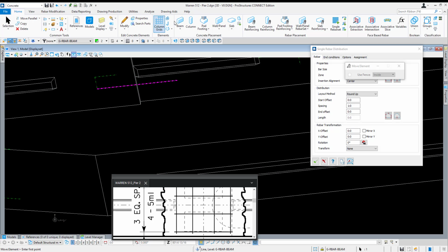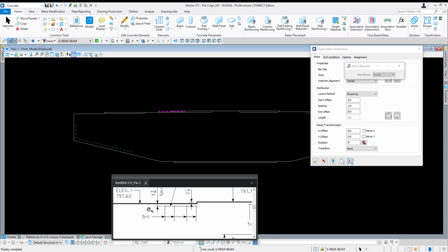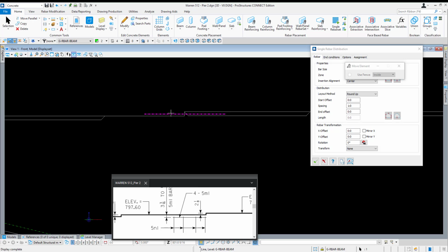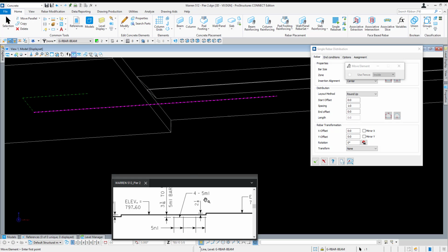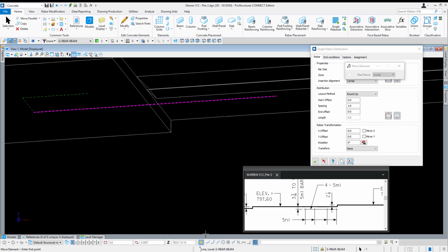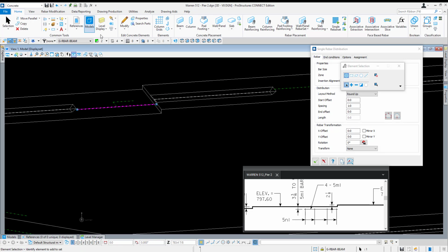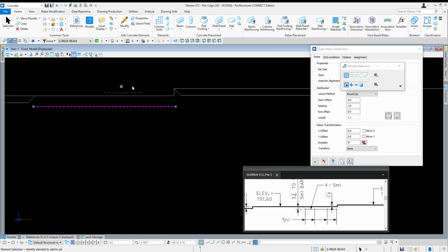Now they are number 5, so right off the bat I need to make sure that I have my clearance values right. And for this set, we need to be 3 3/16 to center line of the 5M1 bars. That's really helpful that that's provided. So first things first, I'm going to shift this bar over to the center point there. Come on, center, snap, there we go. Let's try that again. Move, center, to here. And then rotate to a front view, move it down, and then plus an additional 3 3/16. Perfect, so that's for those.